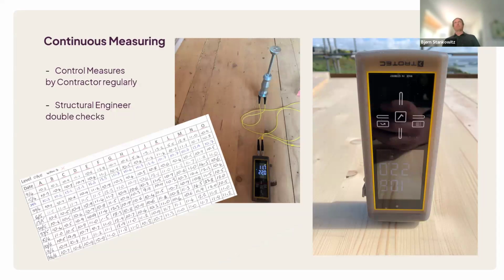And then you come to the actual point of, we want to measure the moisture and see where it's going, to keep control, to make sure that our specifications and what we define to be the limitations and the boundaries are met. So you create these big tables, and you get a structural engineer or someone on site to run around the big mass timber job or your residential job every week to tabulate this and to do your QA.